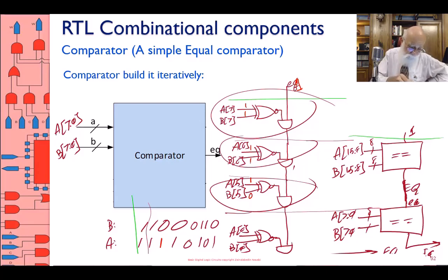So you come in with 1 into the upper bit. Then you get a 1 into the bit number 6. A 1 there gives you a 1 into bit number 5. Bit number 5 ignores the 0 and 1 on its inputs. That's 0. 0 and 1 become 0. And therefore, from this point on, all the ands, regardless of what A and B's are saying, are just sending 0 through, and therefore you get the 0 on the output. All right, that's a cascadable, iterative, 1-bit comparator that only gives you an equal output.